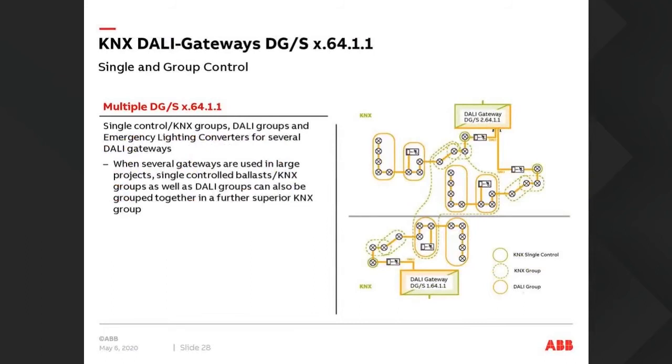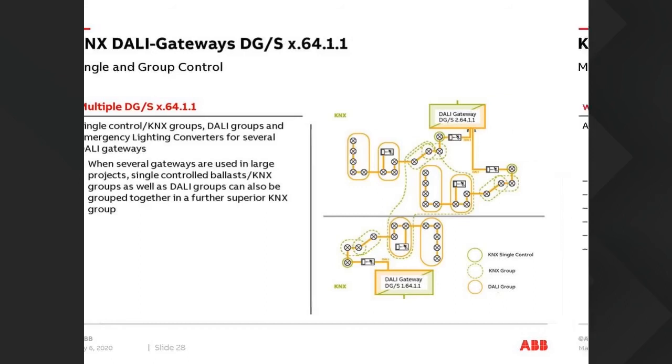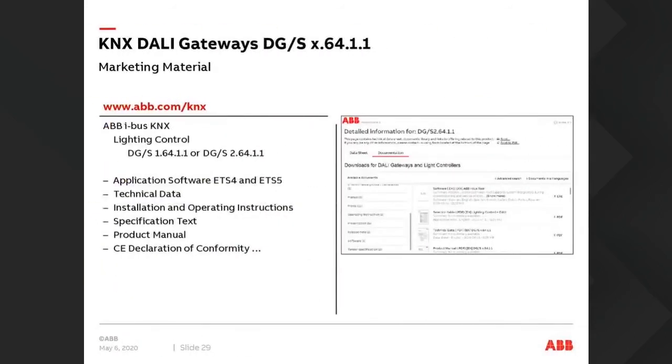And again, if we have multiple DALI gateways throughout the whole system, we could connect one all-off telegram to every group and every fitting. It doesn't take long to do, it's easily configurable, and it gives a lot of control throughout a building. And coming up to the end now, just a couple more slides, and then I'll show you the IBus tool.